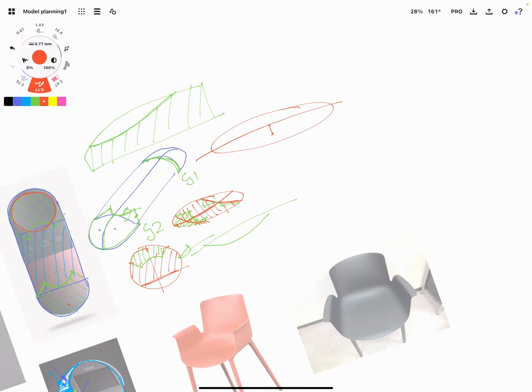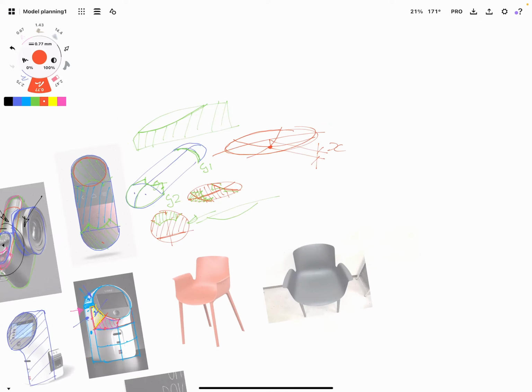You can put a point down a certain distance, whatever that is, X, and then you make a fill surface using SolidWorks, pick the outside, and then as a constraint curve you pick that point, and you end up with a nice even dome going through there.